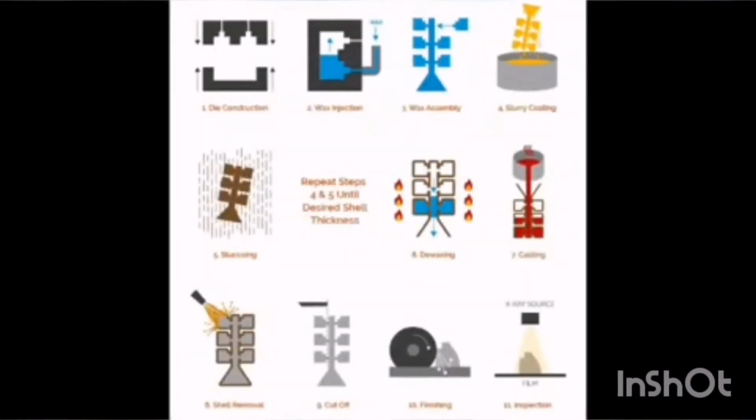The other process to make titanium alloy is investment casting. First thing we need to do is create a wax pattern using the 3D design model with AutoCAD, and then the wax patterns are assembled onto runners into a finished tree which is ready to be dipped.